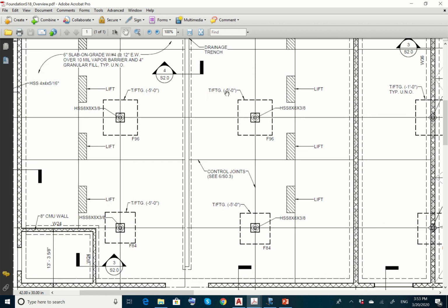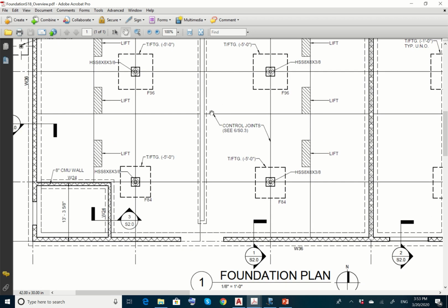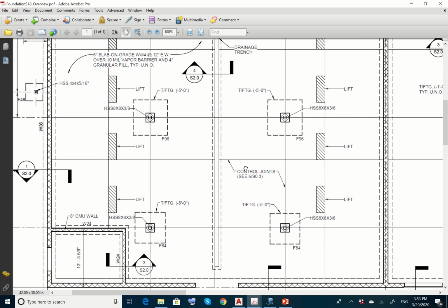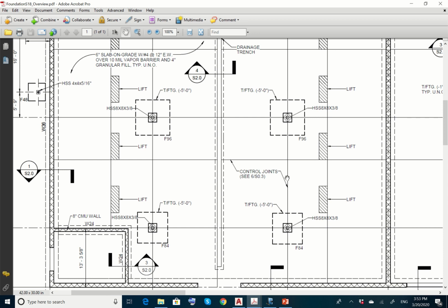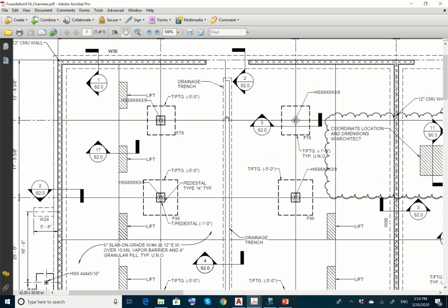You're going to be writing all the text here, the arrow. You're going to be using a leader over here. There is a control joint. Just draw the control joint. The floor is not one part, there is a joint over here to control the expansion. So just draw this, and put the multi-leaders over here. There is this trench over here, a drainage trench. It doesn't mention how much the width is. Just assume anything that is reasonable with that foundation below the trench. Put all those section details over here.